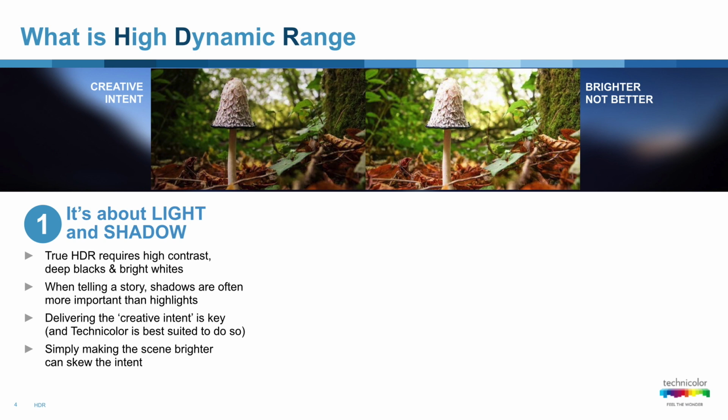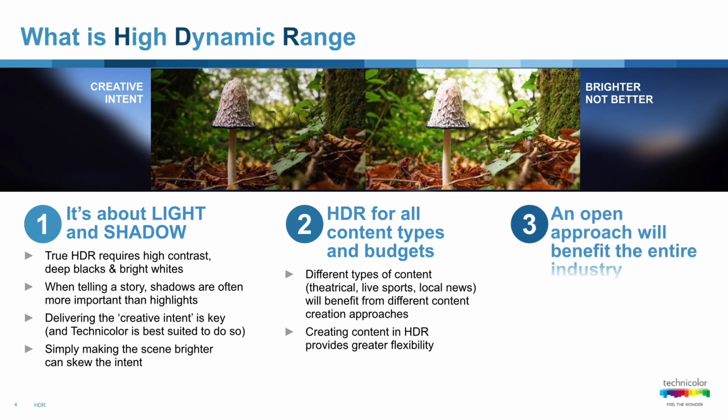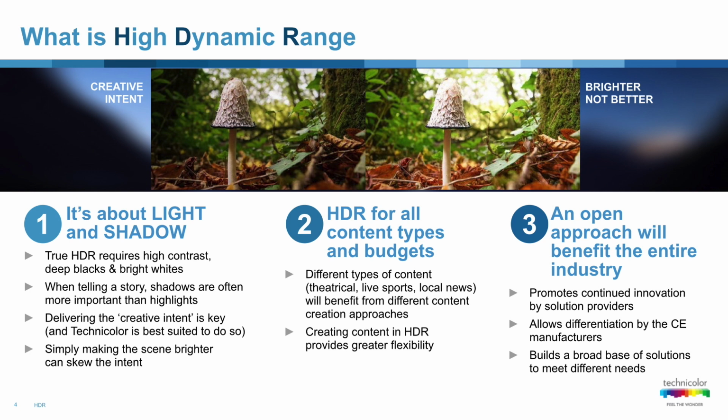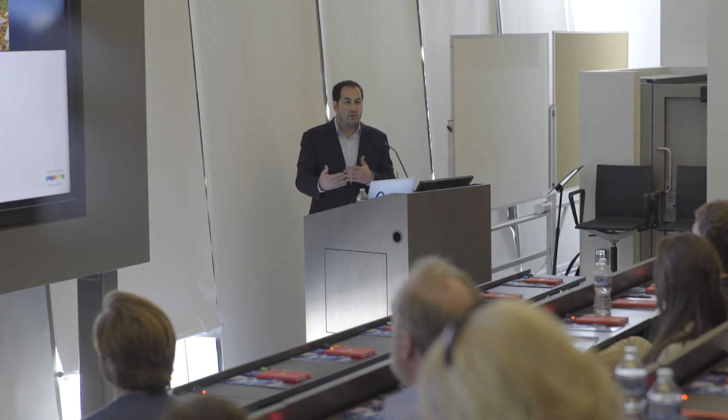What I'd like to point out about high dynamic range is it is all about contrast. It is all about dynamic range. The perceived increase in sharpness, and we'll show you some of this in a little bit, is not a resolution thing. It is because of the contrast and the local contrast within a panel that allows you to see more within that space. It's been described as being seen as 3-dimensional, even when you're not wearing 3D glasses. The reason for this, the perception of more depth, is coming out of that local contrast increase.